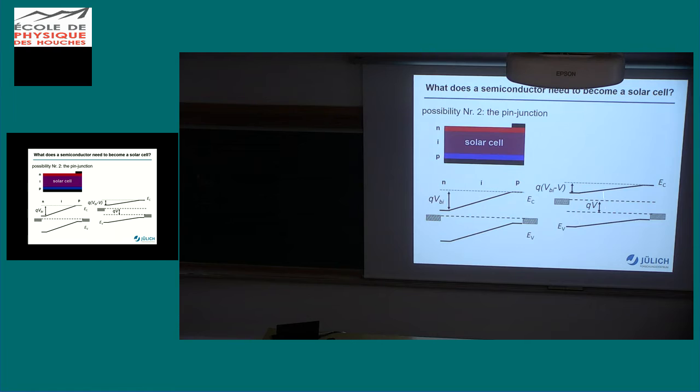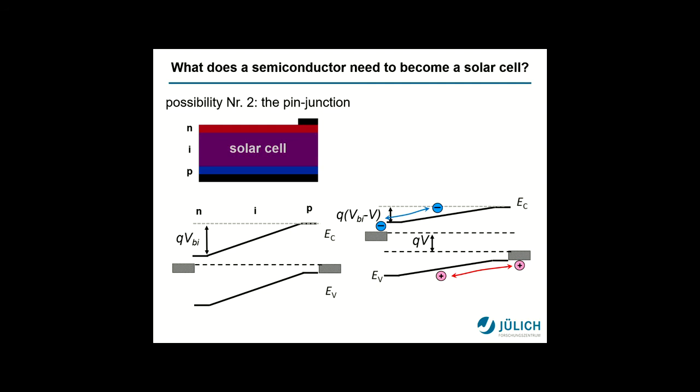Yeah, recombination will happen faster because you have more electrons and holes at the same time. But just looking at the field, it's getting smaller, implicitly. So that's really the power of this built-in field is reduced with your working condition. So that's a critical point in this PIN. If you really rely on the field effect, it's getting weaker and weaker the closer you come to your working condition. And that's one limitation of PIN junctions.